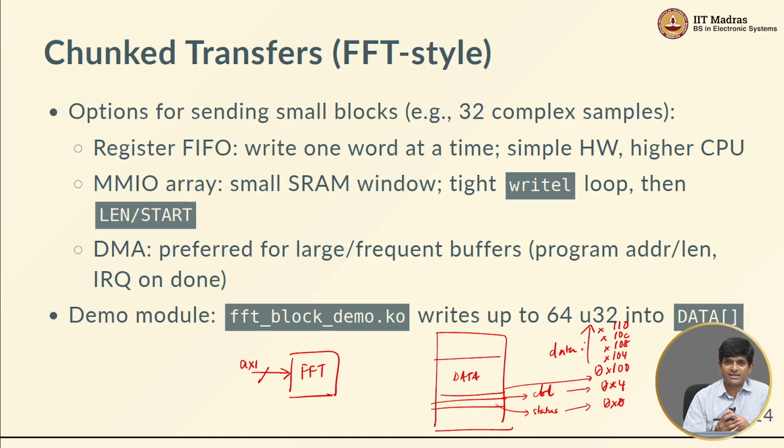What I mean by parallelism is, let's say I'm trying to do a 32-point FFT, I might actually be able to put 32 multiplication blocks inside my FPGA hardware and finish my entire FFT within a few clock cycles, possibly even less than 10 clock cycles, rather than going for hundreds of clock cycles, which is what will be required if I am writing it as code on the CPU.